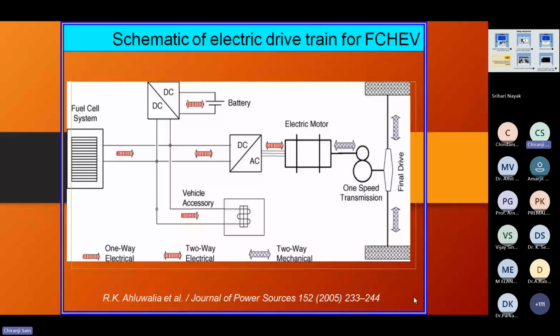So that is one of the important aspects for the EV engineers to look into, the particular operating characteristics of the motoring and braking operation, depending on the multi-quadrant or four-quadrant operation of an electrical drive system, and the dimension of the torque and speed that are going to be controlled in a precise manner, depending on the various road conditions and the transient operation of electrical drives, like starting, braking, speed control, hill climbing operation, and the highway cruising operation, that we need to focus on.